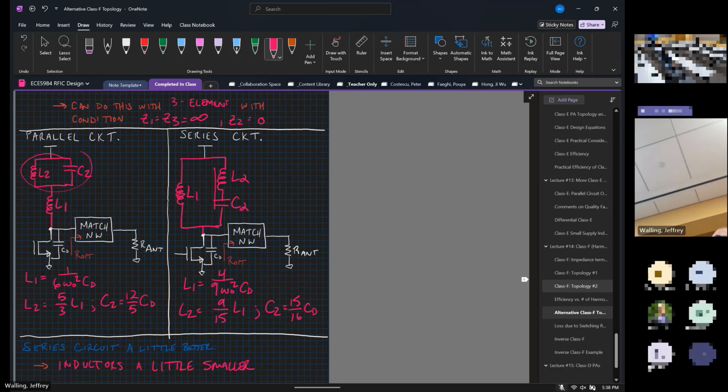All right. In either case, these actually still aren't great. I have two inductors for both of these that I'm going to add in addition to whatever I add for my matching network. Now I can probably try and fold that impedance of that network into my matching network somehow, but it's going to be a little bit tricky.